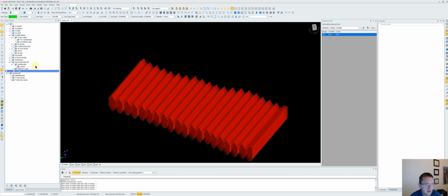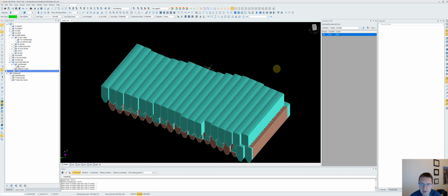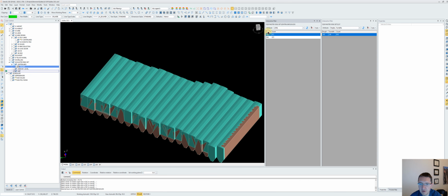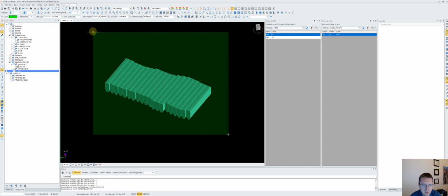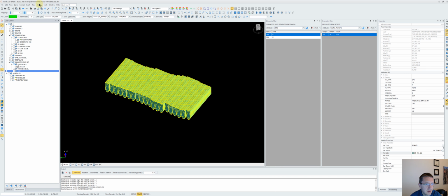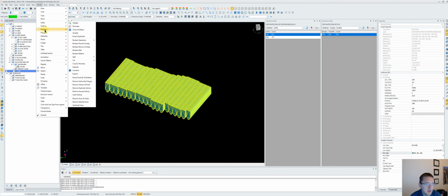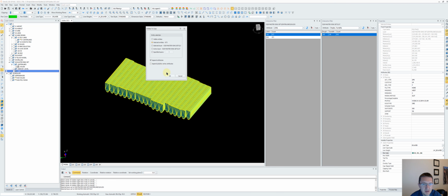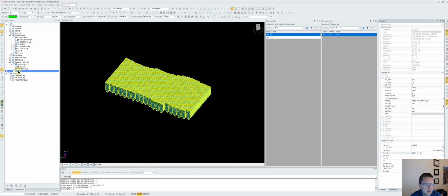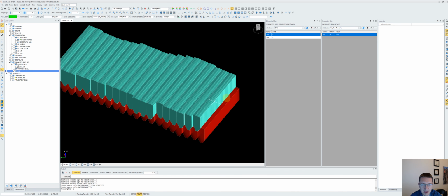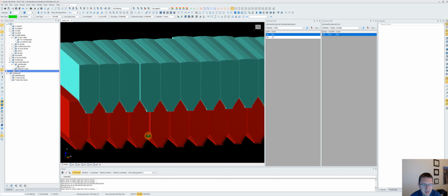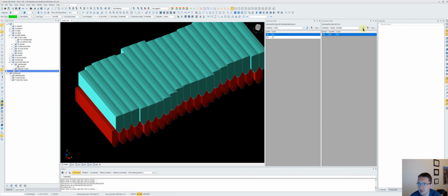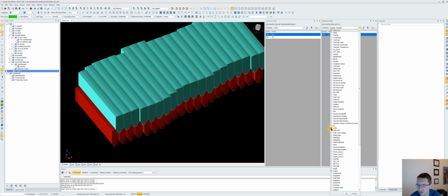Now the problem is we don't have the upper level. So to get the upper level, just bring this on, create an interactive filter. We want the top level, which is the 560. Take all these and go modify, copy to selected layers. Okay. Isolate. Okay, so now we have 2 layers, and the bottom layer should be nice and cut. Let's make sure that's true. The level here.